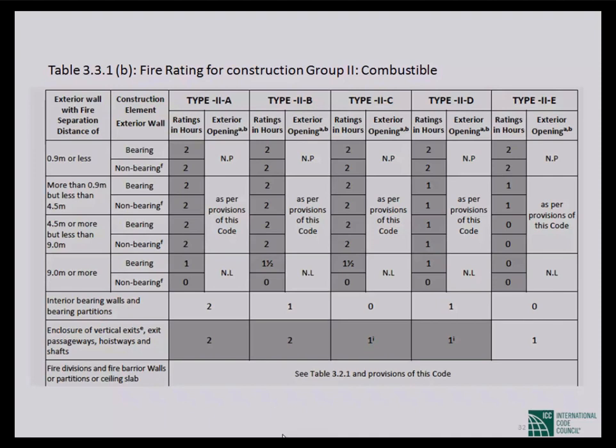So you can see that using combustible material, we can make type 2A or type 2B construction. These are all buildings with different types of rating. Though it is combustible, it has some rating, 2 hour to 1 hour. So combustible material can be used up to this type of fire rating.